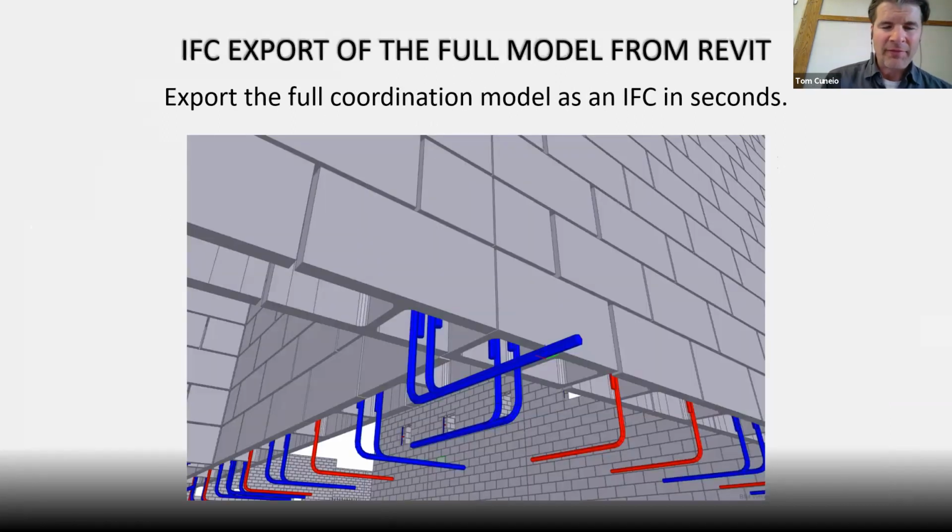As an output from Revit, of course, we've got contract documents, we've got sections, details, all of that. But we can now export an IFC model that can be used for clash detection and coordination. So we don't have to remodel, which there's so much of this happening in construction today. We don't need to have another trade come along and start from scratch and start modeling. We can convert the design model directly into an LOD 400 model for coordination.